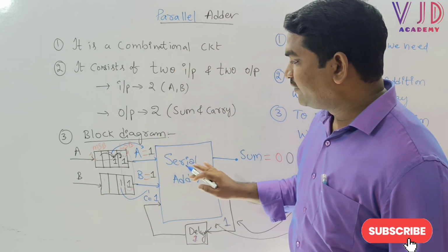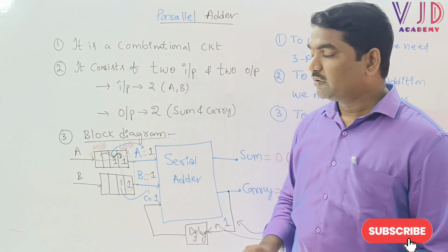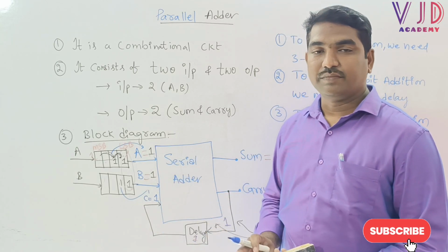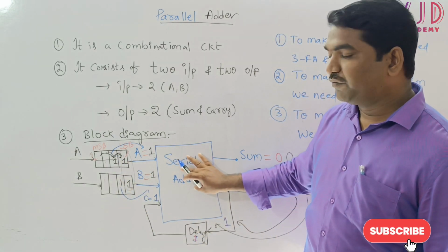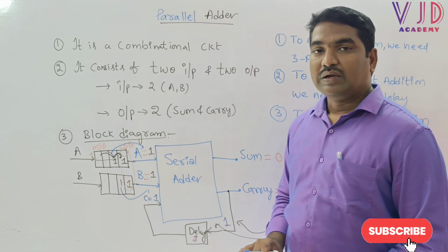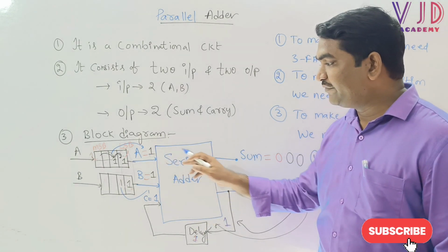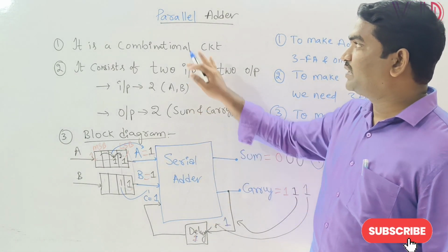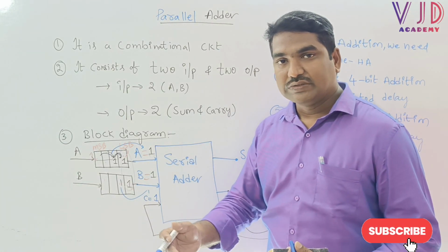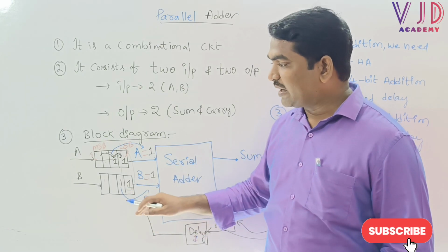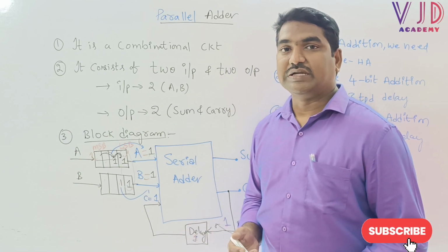In the serial adder, only a small number of bits can be added at a time. And second, we need shift registers and delay blocks and even full adders and half adders to make the addition. Also we have a huge delay for every addition. So to overcome this, we are moving forward to the parallel adder. In the parallel adder, we will apply inputs in parallel instead of serially, so that the output is possible to get instantly.